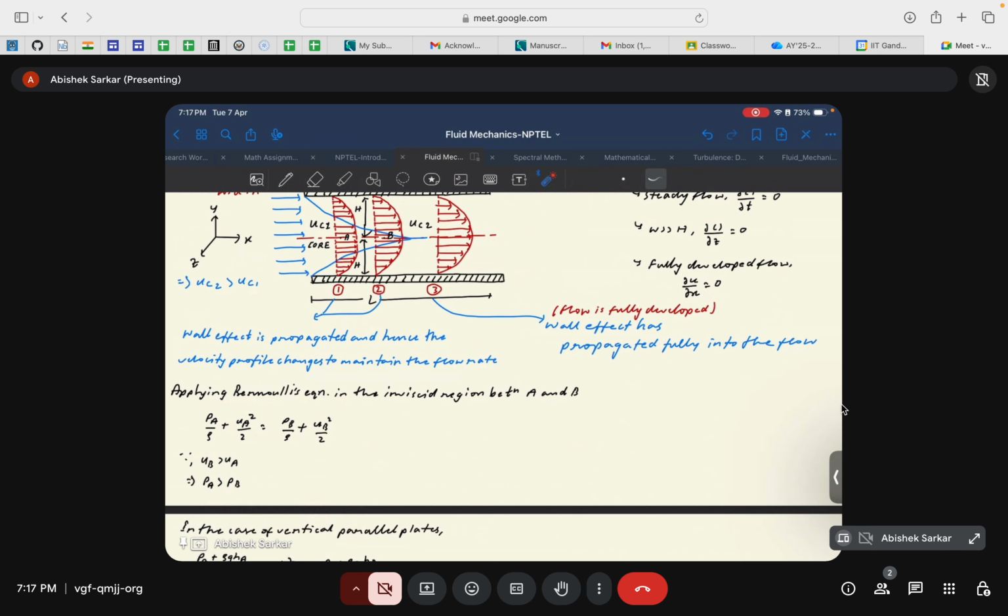Okay. So this pressure being lower at the downstream end of the duct, to encourage the accelerating of the flow or generate the flow, is indeed known as the favorable pressure gradient. In terms of derivative, dP by dS would be negative. You can write something like PB minus PA divided by LB minus LA, and since PB is less than PA and LB is greater than LA, it is negative. In terms of differential, it is dP by dx, which is equal to negative.